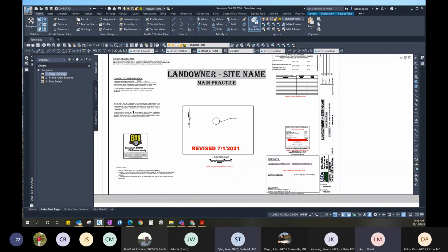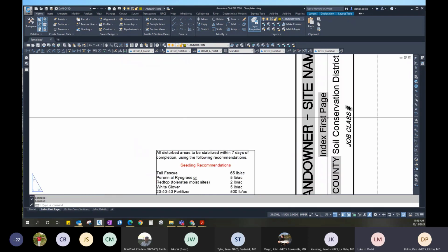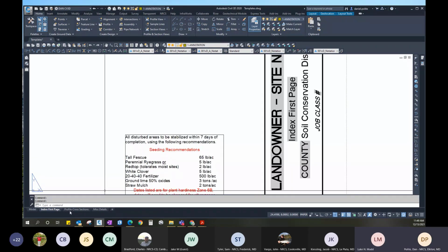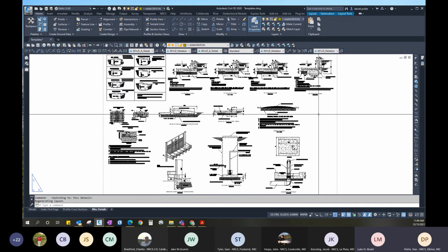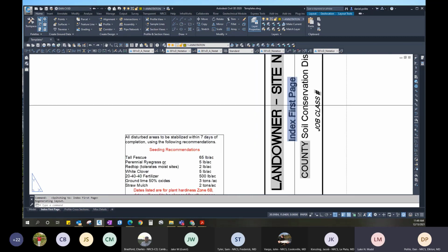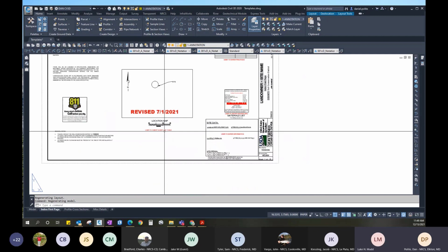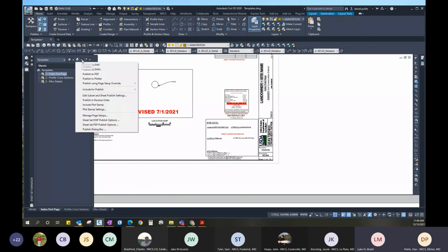What are the benefits of a sheet set? Well, I'm going to show you. So basically, the one nice thing, did you see what happened automatically on this? It put my names of those sheet sets automatically into, well, it didn't do it on this one because it doesn't have a thing, but whatever this name is, it's going to pop it into those hashtags automatically. The other nice thing is inserting your actual table. So you can come down in here where the little plotter is.